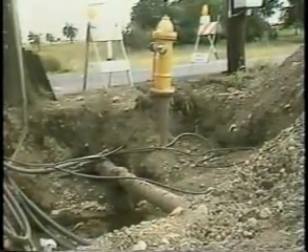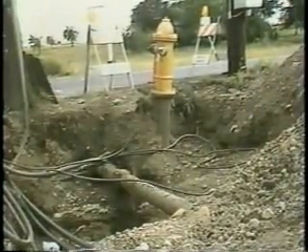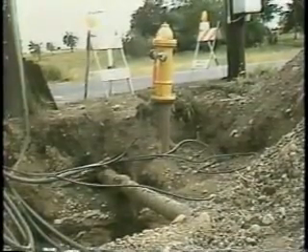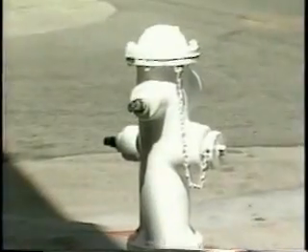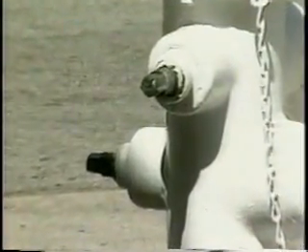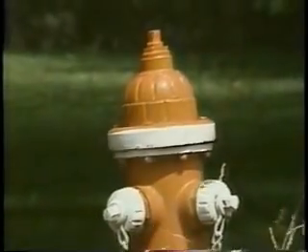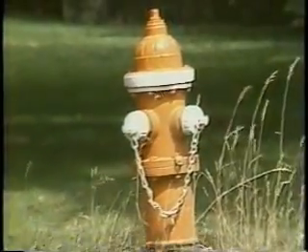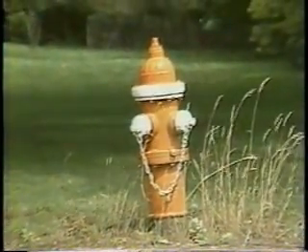Man-made water sources include hydrants, which are taps into water distribution grids buried underground. Hydrants found in warm climates are generally the wet type, where freezing is a rare occurrence. Valves are placed high in the barrel of the hydrant. Dry hydrants are usually found in cold climates.